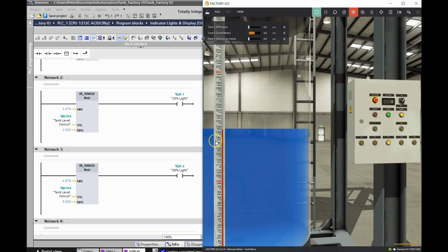And I wasn't sure why that was, and I took a closer look, and what I had done was I had put 4.475. So if we take 0.4475 and we multiply that by 300, that's 134.25. So way down at 134, 135, that's when my indicator light was turning on. So I changed that. It must have been on cruise control and looking at that value right there.